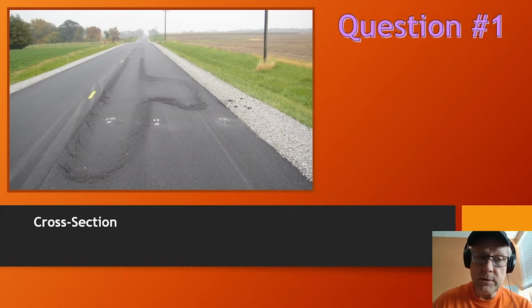In this case here, the question would be, how come the pavement's only failing in one direction? Be a good question. What you don't know is this is a farm to market road. The grain silo is into the picture, so all of the heavily loaded tractors would go east in this particular case. What you also don't know is this is a brand new roadway that required a lower course and an upper course. The upper course was uniform, but in order to build the pavement with the proper cross section, the engineer specified a much thicker lift of asphalt at the middle of the roadway. And when that portion is an unconfined joint, the density that's achieved at that location is not going to be adequate to carry the load.